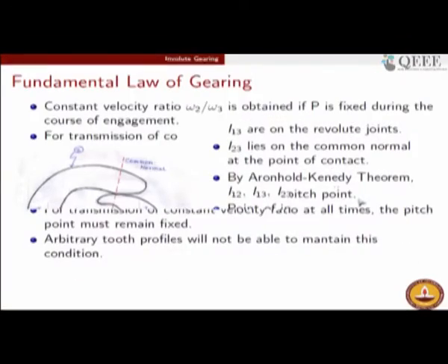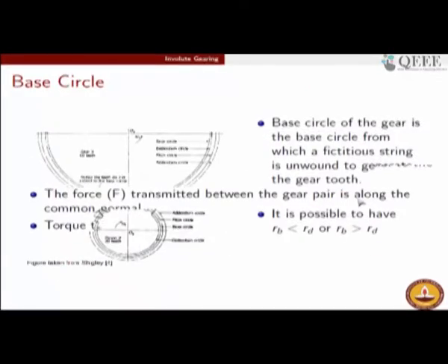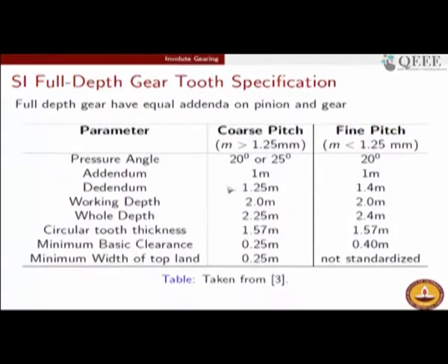What is the role of module of a gear in power transmission? Module of a gear is an important concept in terms of standardization. All the gear geometries are getting referenced. I can possibly show you the result. Okay, I think in one of my later slides I would have these gear geometries being standardized. Yeah, so these are the standard dimensions of a typical gear. As you see, the M here stands for module. It is not meter, right?